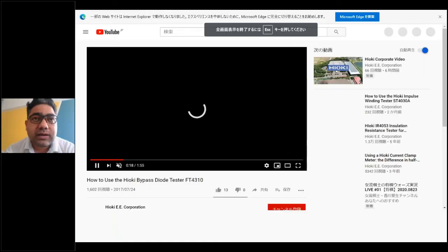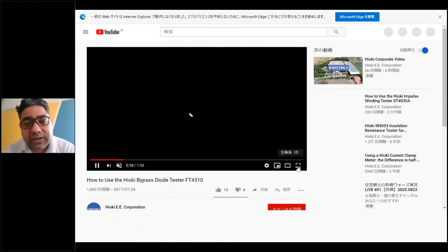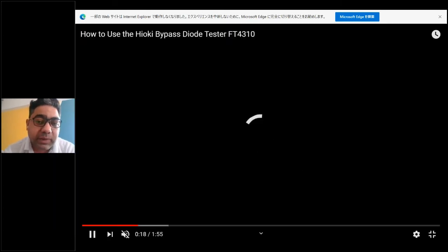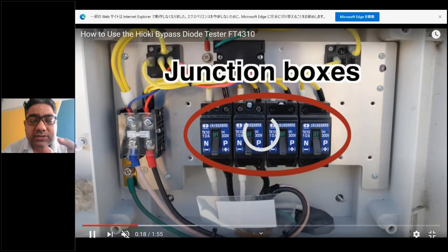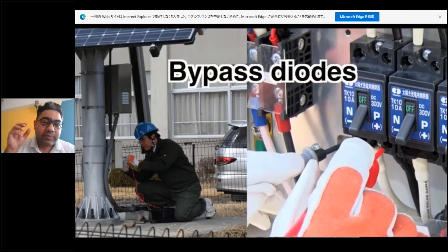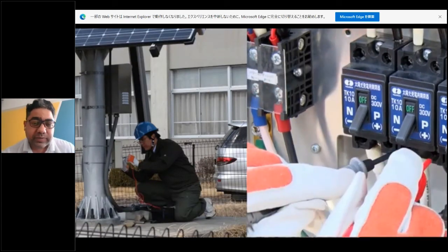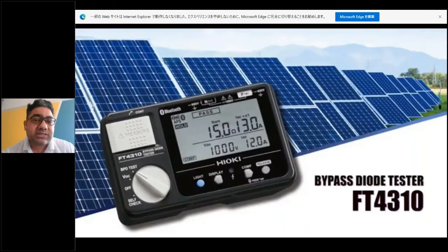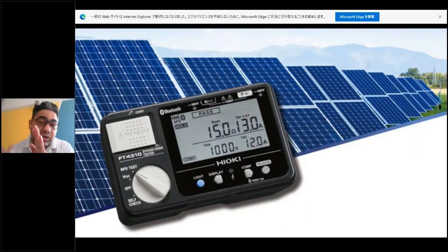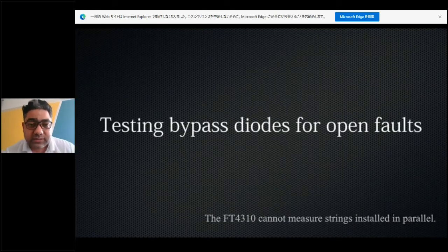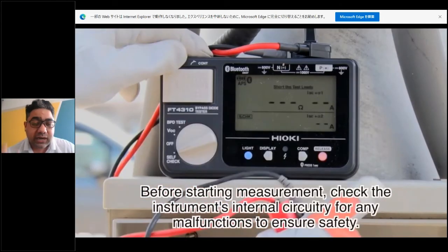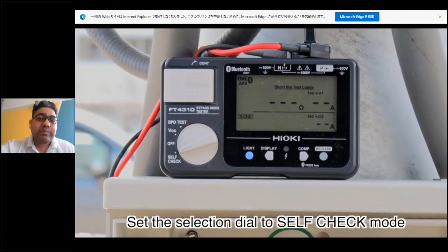Inside the solar panel, the cells are connected in series. Along with that series, on the parallel side, there are bypass diodes. If any particular cell, for example, has dirt on it or some shade comes up, then that particular cell will start behaving like a resistance, which will not allow the current to pass through that particular series. At that time the bypass diode comes in and bypasses that particular series of cells, and the current can pass to the next cell.